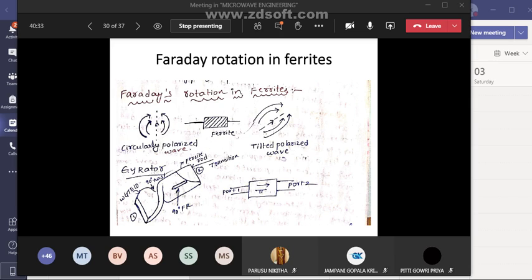And a thin circular ferrite rod is located inside the circular waveguide, and the waveguide is surrounded by a permanent magnet which generates a DC magnetic field for proper operation of the ferrite. And this ferrite rod is tapped at both ends to reduce the attenuation.